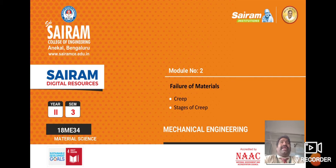If you take any mechanical strength of metals, it decreases with increasing temperature, and the properties become more and more dependent upon time. For example, any part of a furnace, turbine blades, or steam generator are all subjected to heavy stress at elevated temperatures. The deformation of components under such circumstances is termed as creep.